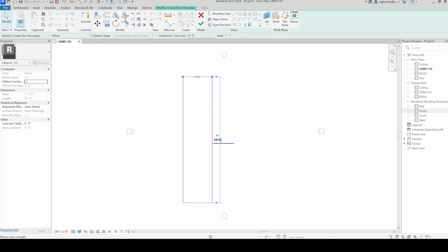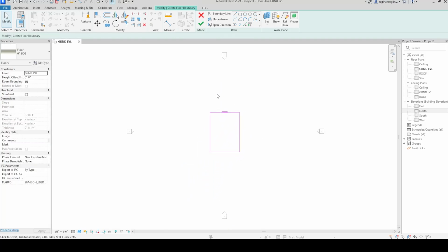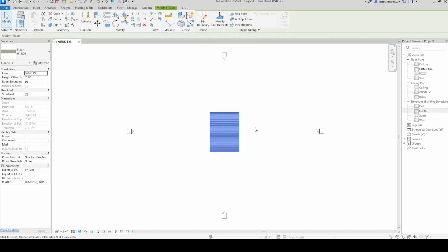Revit has the awesome capability where you can input feet by themselves, put a space, and put your 6. If I'm dealing with half dimensions or even a quarter, you can type that out by doing an additional space and putting in the fractioned dimension that is needed. I like to do it where I just put in the decimal, but everybody is different. So pick which one is easiest for you. I like to highlight it, move it a little closer to the center, and hit the check mark.